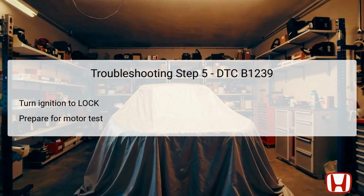Once the presence of DTC B1239 is confirmed, the ignition switch should again be turned to the lock position. This action prepares the technician for the subsequent test of the front mode control motor. Proper isolation of the component is fundamental to prevent any unintended electrical surges during testing, ensuring safety as well as accuracy in measurements. Confirming the ignition is off allows for a safe testing environment where connections can be safely accessed